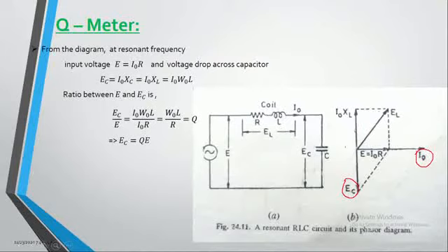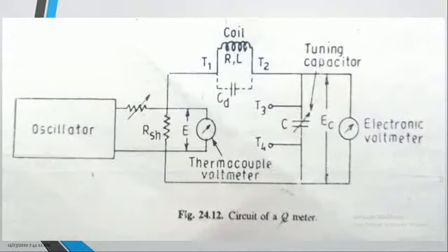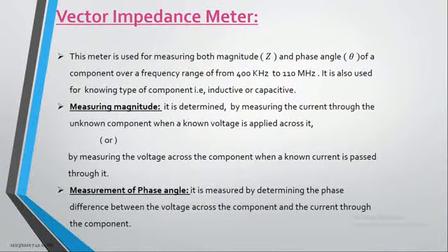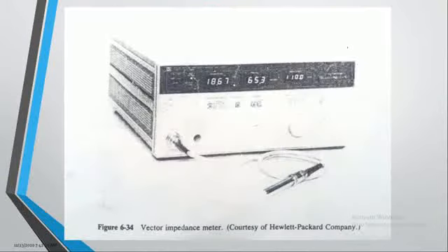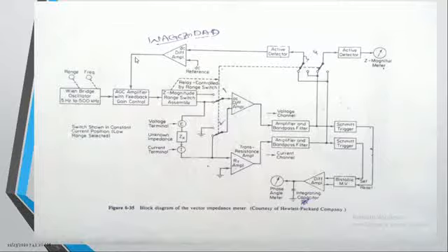When you are placing the voltage and the current phasor on the phasor diagram, if the current is the leading factor and the voltage across the unknown element is the lagging factor. Better I'll come back to the diagram itself, because it is already drawn. Here we are interested to know whether the element is inductive or capacitive in nature.